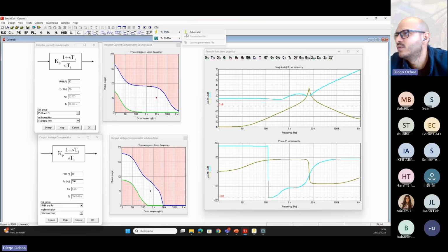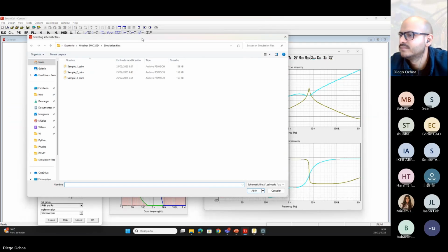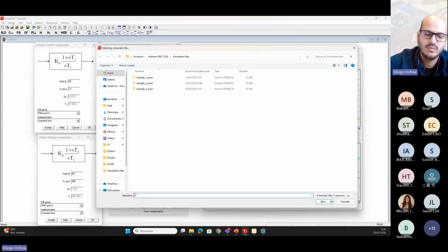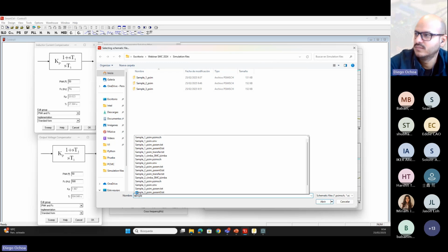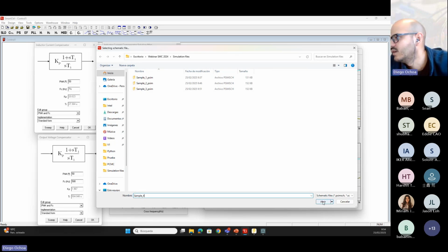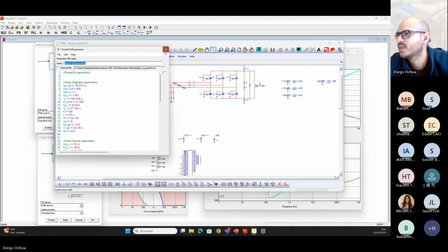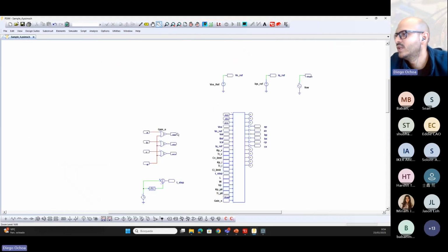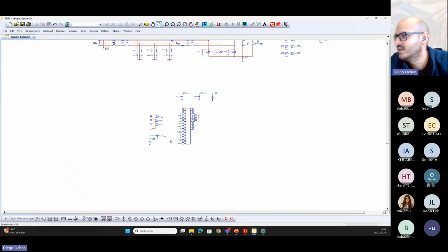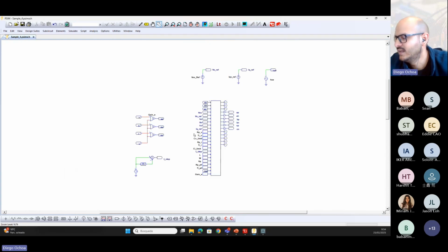For example, if you go to PSIM simulation, go to schematics, I can set another name, number 4, click on open. You have the option that is called C code. If you click on this option, in that case, all the control structure is implemented in the DLL block.